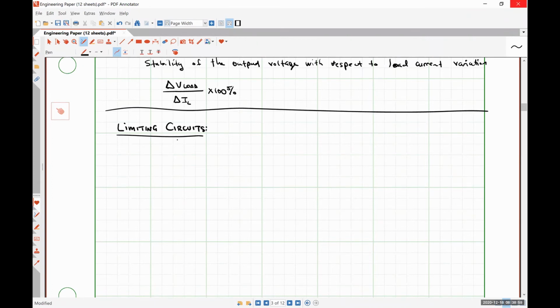So that means that the voltage present at my antenna on my cell phone is going to be at a significantly higher value. Well, that would mean that if there weren't such things as limiting circuits, the closer I got to a cell phone tower with my cell phone, the more likely I would fry the internal circuitry of my cell phone because I'm too close, right? So my voltages could potentially exceed the ratings of the components inside. So we can use diodes to limit the circuit in order to force a particular voltage drop to occur.